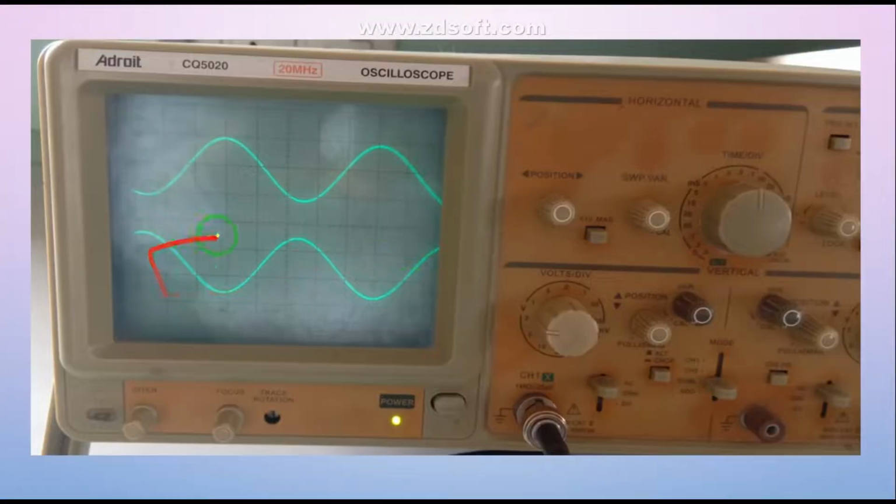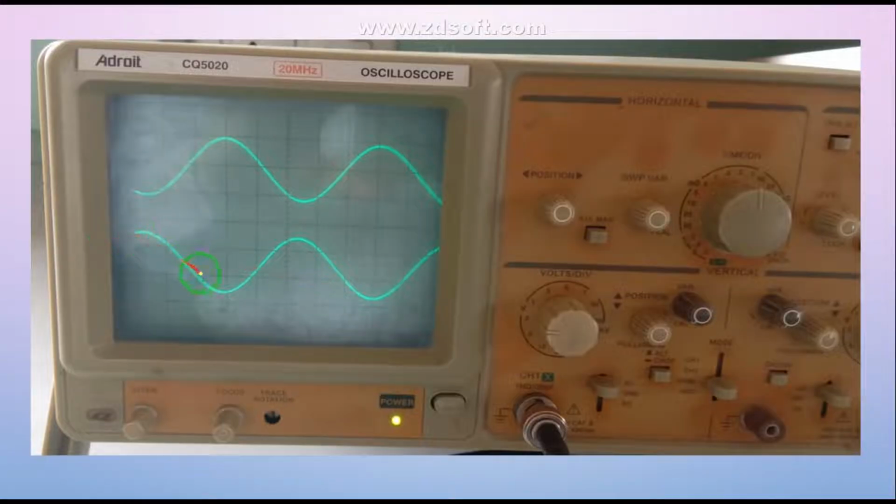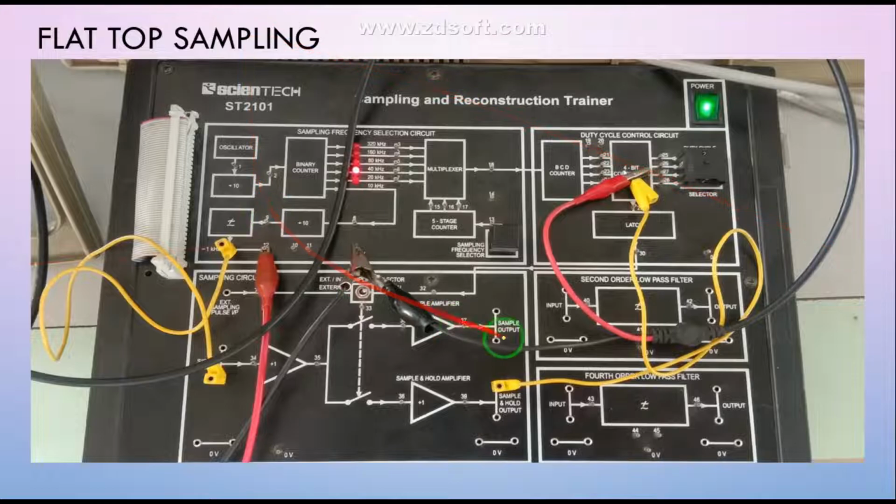Again, if you increase the sampling frequency towards 160 or 320 kilohertz, you can observe the output is recovered. The output of the low pass filter is almost the same as the input that we transmitted. So that is about natural sampling.